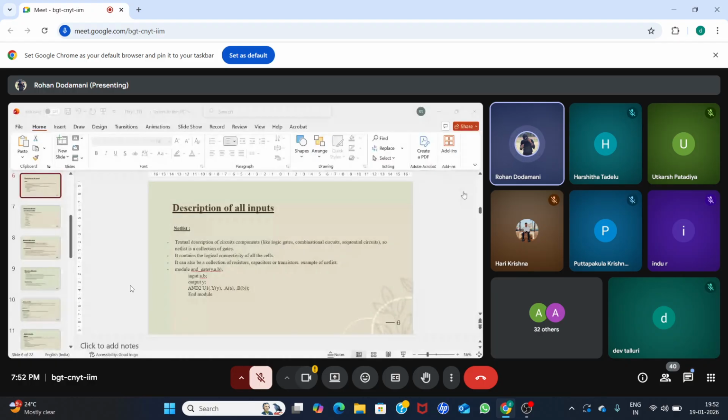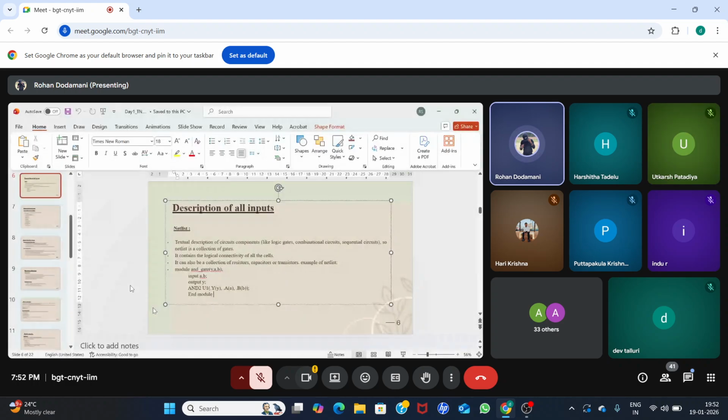If we wrote empty modules, those modules create what we call extra empty cells during the physical design. While importing the design, unnecessarily one extra cell will affect our chip, right? Because that cell needs a location and some area, and it needs power and ground, everything. But there is no logical or physical connectivity for that cell because it is an empty cell.